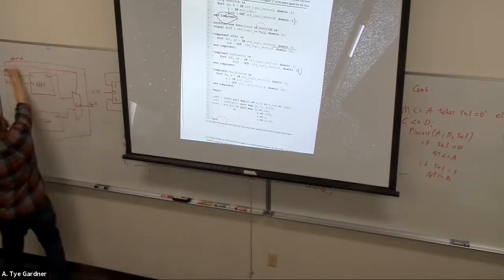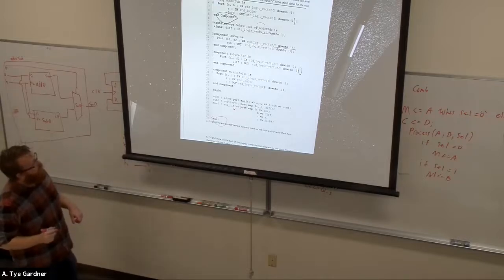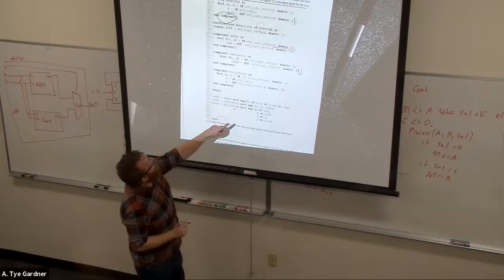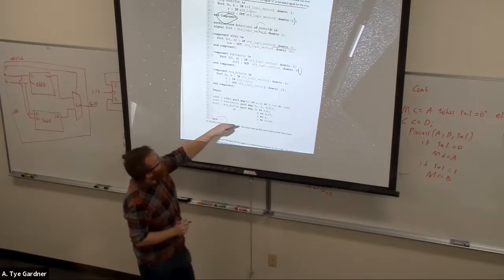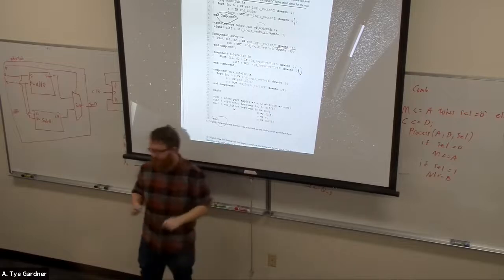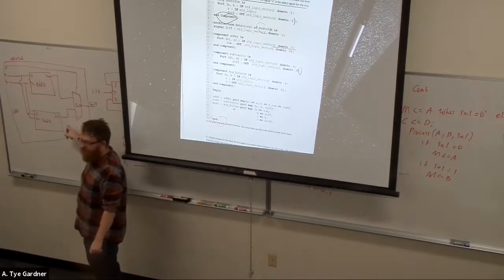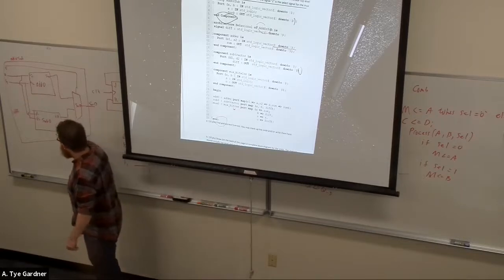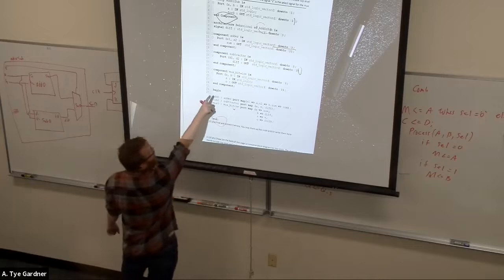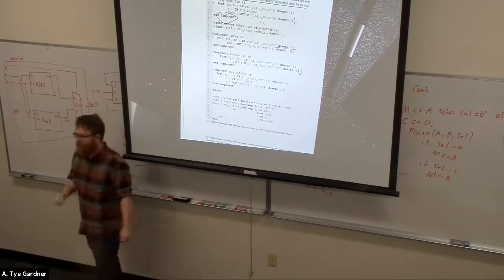Trying to wire B to an output, so that's an error too, right? The map to diff, because diff's on the right side, and it's an out. Port diff of subtractor. Diff is an output of here, but input to the mux. Okay. So that's diff. This signal is called diff. Oh, the port is called diff. This signal is called diff. And this port is the mux's port, which is port B.